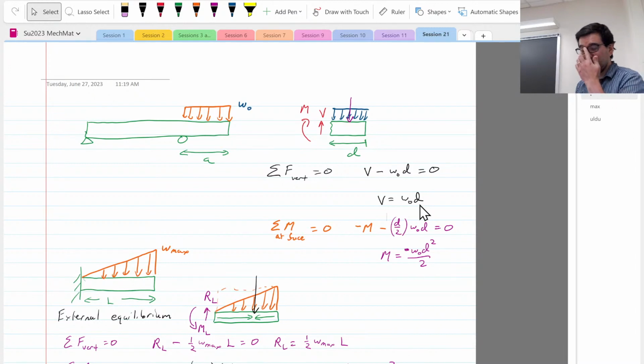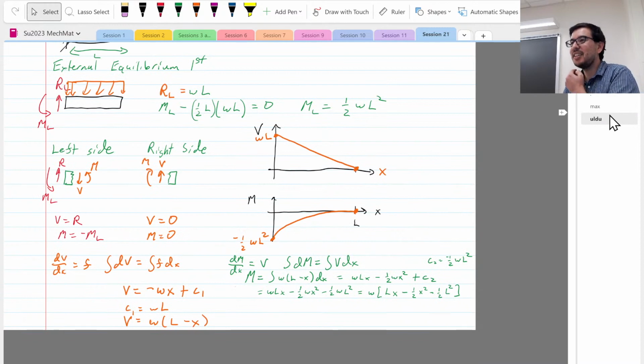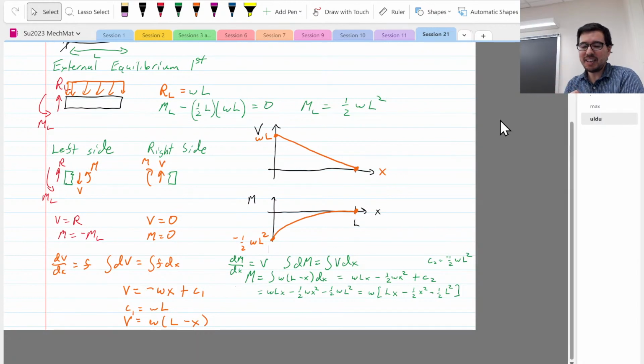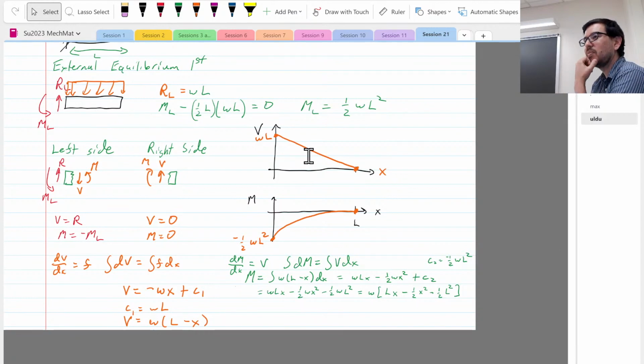Also, to do the bending moment diagram, can I just look at the area of the shear force and then do the changing moment, take two points and look at what type of curve it is? That way I don't have to derive another equation for bending moment. Sure. An integral is the area. This is an expression that's helping us understand the area under the curve. So if it doesn't ask specifically for an expression, I don't have to derive it. Right. And if it asks for a maximum,